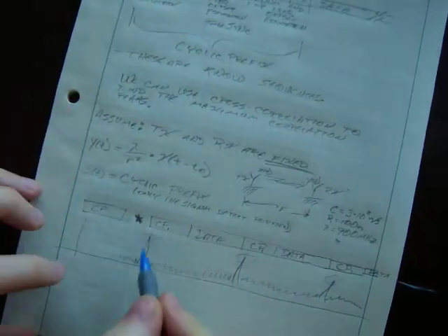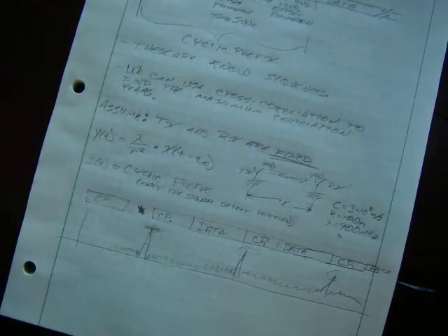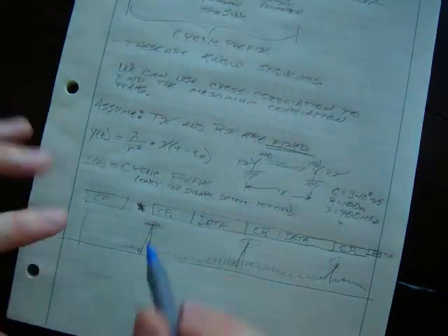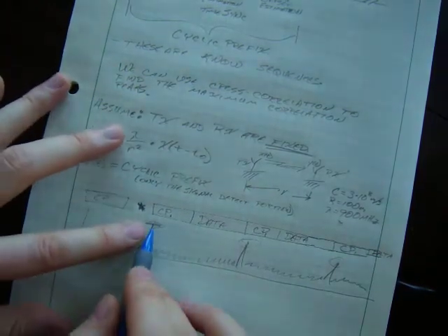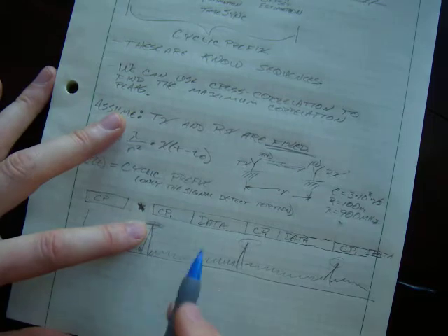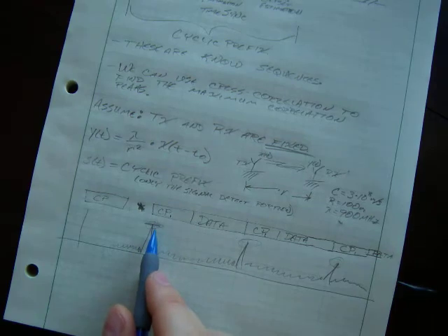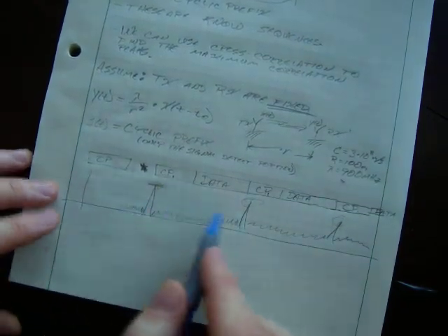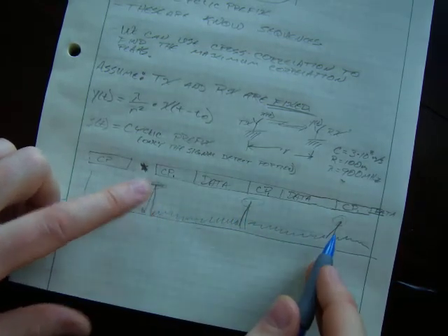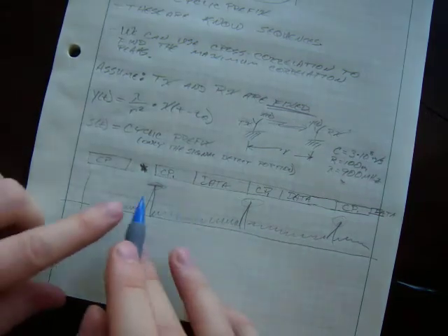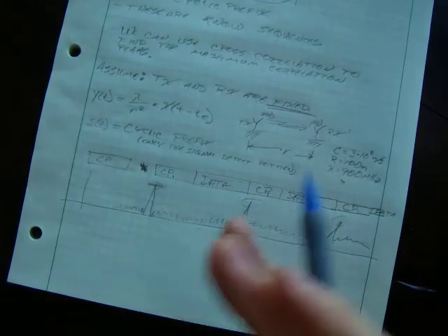They will look at the peak value of this, and then they will adjust the automatic gain control voltage in order to make sure... well, they're actually looking at the voltage on the receiver, not the correlated value, but they're looking at this peak voltage on the original signal at this point of time of correlation to obtain what they need to set the automatic gain control hardware to. The rate of these guys starts to give us our frequency, so the coarse frequency. They can look at the rate that these are coming in and see if they need to do a coarse frequency adjustment.